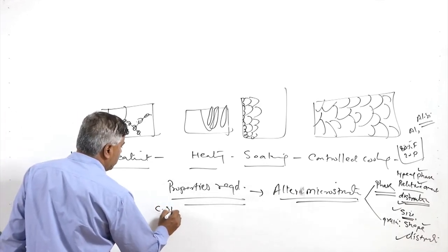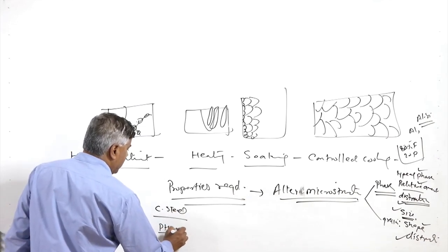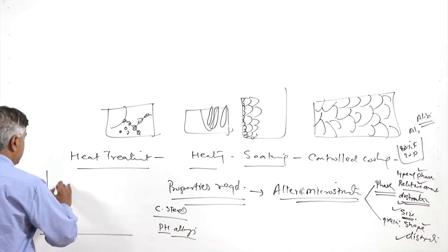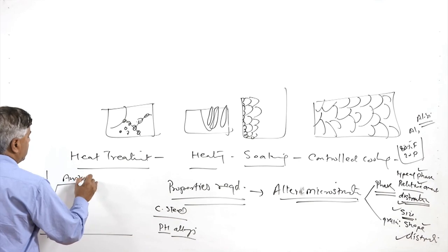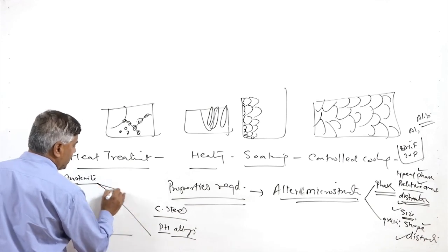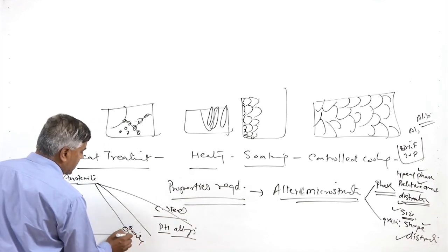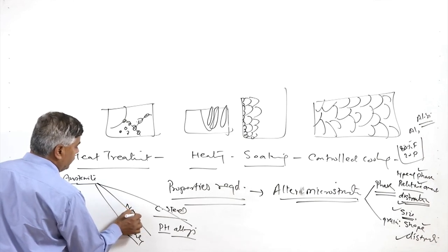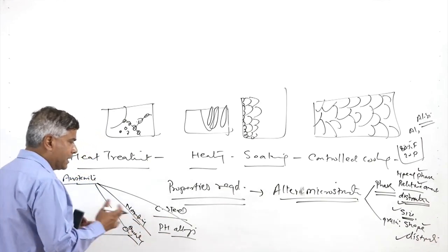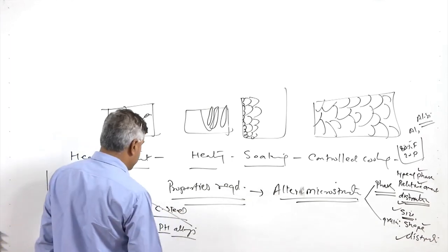For example, most of the steels are heat treated in one way, while the precipitation hardenable alloys are heat treated in a different way. The heat treatment cycle for steels mostly follows heating for austenitizing, so that the entire bulk material is austenitic, and then we allow cooling at different rates as per the kind of heat treatment which is performed. The highest cooling rate is used for hardening, wherein quenching is carried out. Then a somewhat lower cooling rate is applied for normalizing, so that only the grain structure is defined, and then further lower cooling rates are used for annealing, so that a softer structure is obtained.